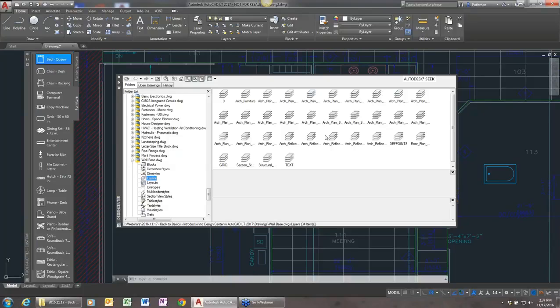For sure, and same thing with text styles and line types and all those things. If you copy a dimension that has a particular dimension style, it's going to bring the dimension style with it. But you can bring just the dimension style into a drawing without necessarily bringing any existing dimension objects that are using that style. So it's head and shoulders above copying and pasting for sure.